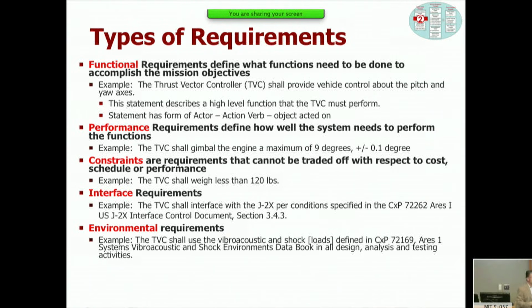So this is a big deal in practice, and at least in space systems design, a lot of these environmental requirements are of course driven by the space environment or the launch environment. If you're designing airplanes, whether you're flying in a small mountainous country like Switzerland or on the ocean off of an aircraft carrier, those are very different environments. You have to specify the operating requirement. The bigger the envelope that you make for the environmental requirements, the more complex the system will be.